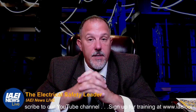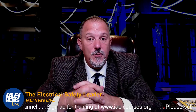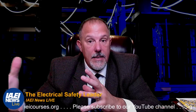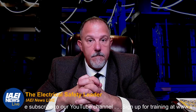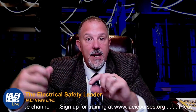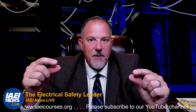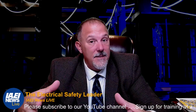And what do we do when we increase a conductor size? We're adding more material, more copper. What does that help us do? Take the heat out. It helps us take the heat out of the enclosure, get heat off of the breaker. And if you're not going to have the conductor get the heat out, then you have to construct the panel differently, possibly the circuit breaker differently. That's why the bus might have to be a certain dimension. That's why the enclosure might have to be a certain size. But heat.